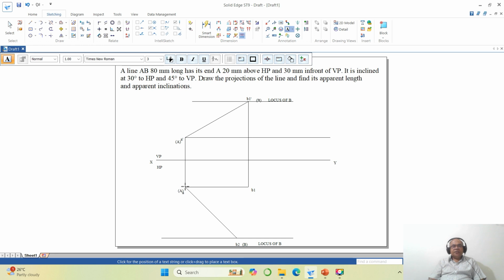Okay. Now I want to get this point. Here this is the front view line, this is the top view line in true length. To this the front view line has to be parallel. You don't have a front view now because you have only a dash. You don't have b2 dash. I want to create that b2 dash. Where should that b2 dash be? b2 dash should be in line with a dash. Then only a dash b2 dash is parallel to xy.